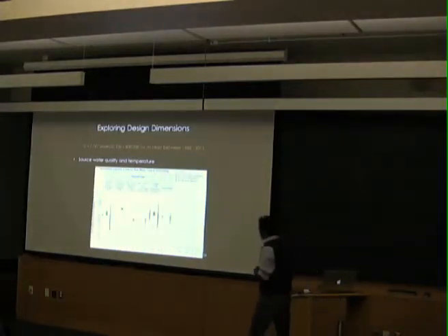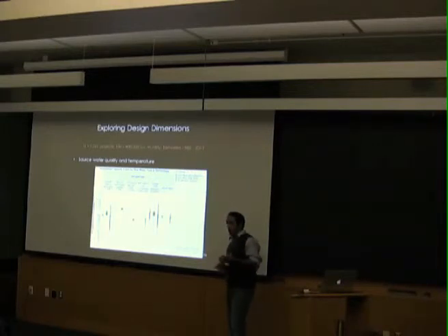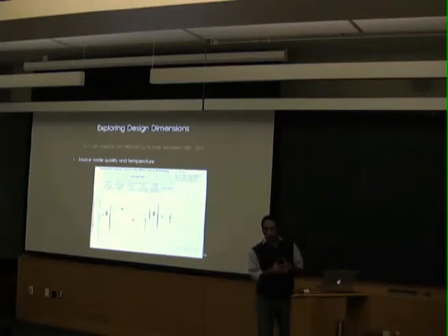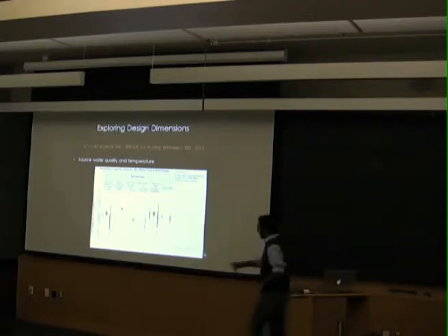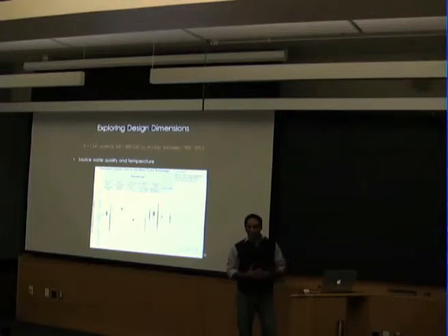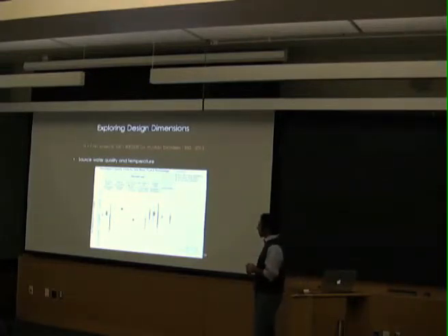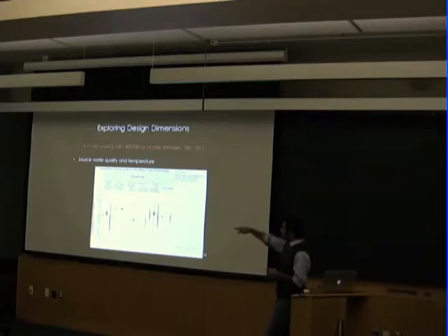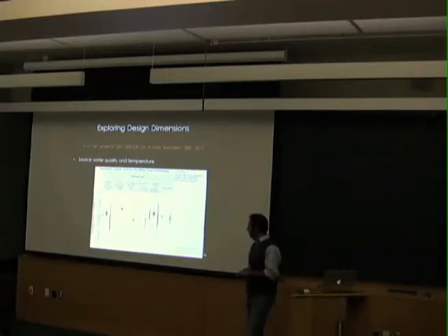So this chart shows the unit cost, so dollars in terms of cubic meters a day of capacity of the desalination facility. On the very left, the column shows brackish water and inland water, which has the mid-range of TDS. So you could take that as a benchmark or a reference. If you looked at brine or highly concentrated seawater, you'd see that the cost per unit of production capacity moves up. But if it's river water or low concentrations of saline water, cost might come down. So these charts show some of the probability distributions and what you'd expect in those unit cost numbers.